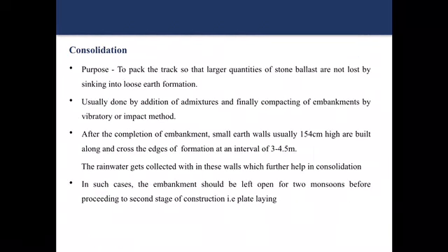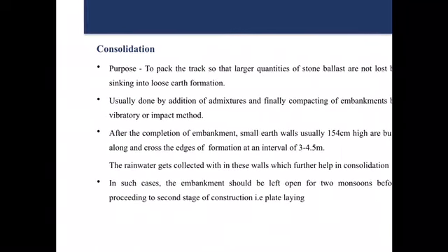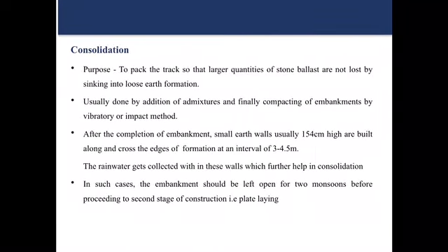The next step is to go for the consolidation. Why is consolidation required here? Once you prepare the formation, there are chances that the formation level you have constructed may undergo volume changes because of the variation in the moisture content.